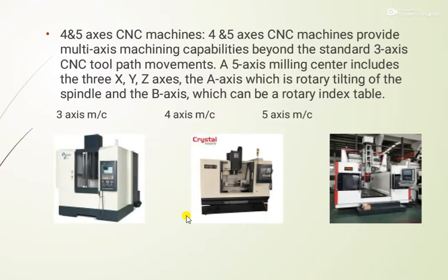The multidimensional rotation and tool movement allows unparalleled precision, finish, and speed in the production of a piece. 5-axis machining can create very complex parts, which is why it is so important for high-level uses such as aerospace applications. 5-axis machining is also becoming more popular because it offers the option for single-step machining, allows better access to part geometry, and improves the tool life and efficiency of the process by tilting the table for the ideal cutting position. And that is about 5-axis.